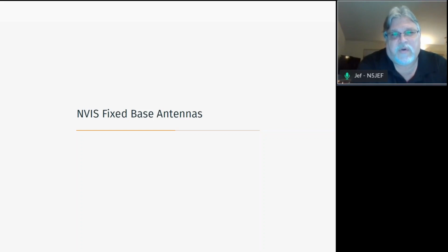If you're looking for a 10-meter optimization, then half that height. Again, in real life, we all know that whatever antenna you have is the antenna that works. I mean, depending on the conditions, it'll work. But at whatever band you're interested in, a half wave off the ground for a horizontal dipole will give you those nice wide side lobes for DX.